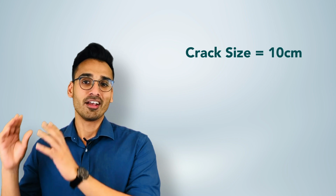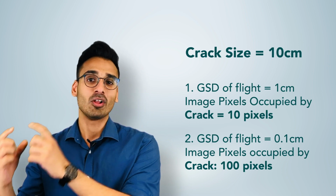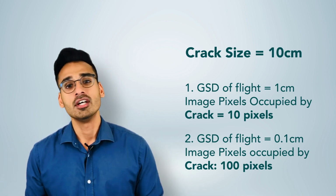So what I'm going to do here is throw in some parameters which show you essentially the image size, the GSD, and what every pixel on a particular wind turbine or asset might look like, and how big or small it might look depending on the GSD of your capture. So the key concept here is that when you're looking at inspection use cases, the GSD has got to do more with how big or small objects look in the final images, as opposed to the accuracy of the data, because you're not really doing the mapping side of things. So once again, GSD, very fundamental concept, but has different implications depending on your end result or your end outputs.